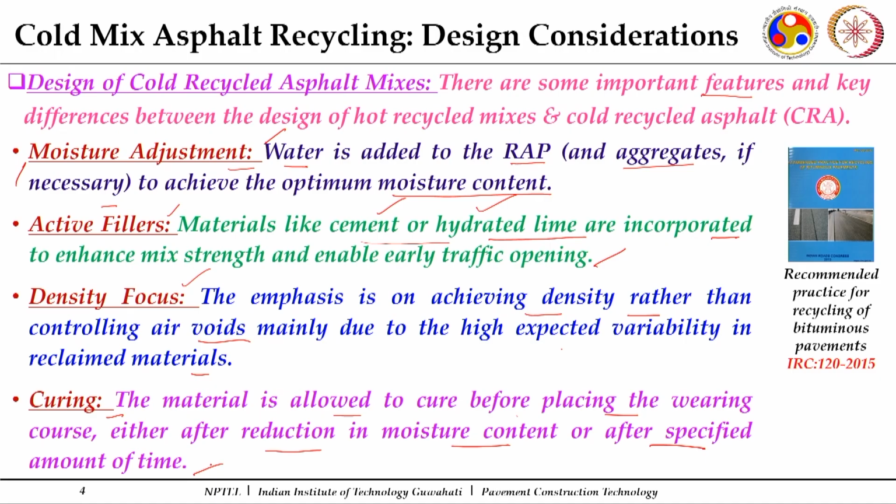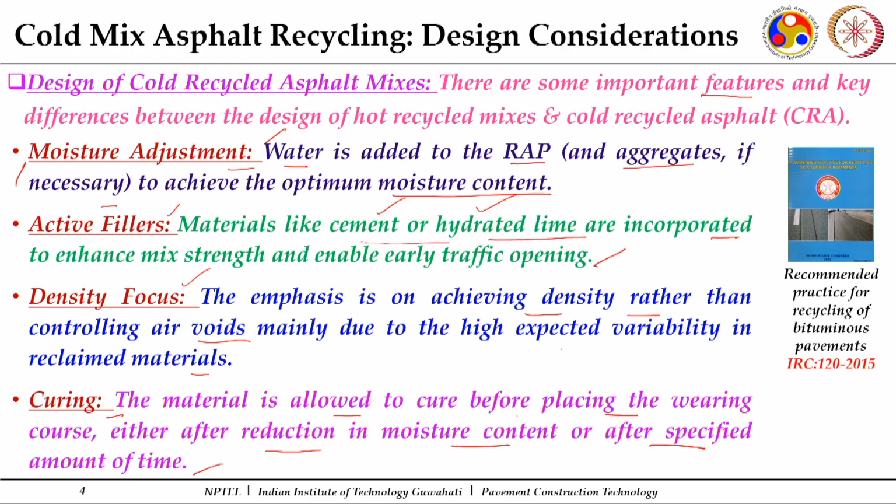So either you go, as mentioned in the earlier talk, in the case of, say, foamed bitumen stabilized base courses, you will see how much the water content has gone down, so that the surface has reached a particular level of dryness, and only then can the wearing course be applied over it. Or it has gone through a given period of curing, which may be 3 days or 7 days, after which you apply the wearing course. So these are some main differences in the design of cold asphalt recycled mixes compared to what you have in the case of hot mix asphalt.